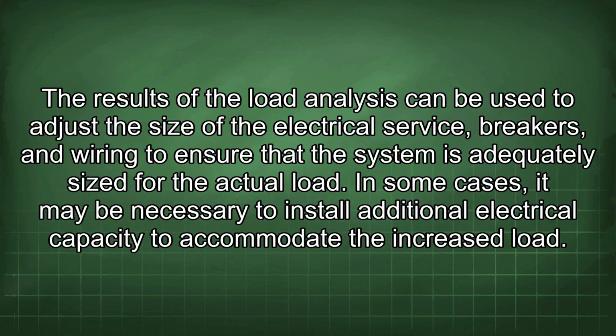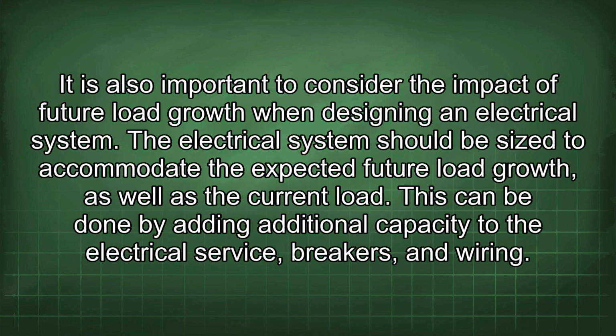The results of the load analysis can be used to adjust the size of the electrical service, breakers, and wiring to ensure that the system is adequately sized for the actual load. In some cases, it may be necessary to install additional electrical capacity to accommodate the increased load. It is also important to consider the impact of future load growth when designing an electrical system. The electrical system should be sized to accommodate the expected future load growth, as well as the current load. This can be done by adding additional capacity to the electrical service, breakers, and wiring.